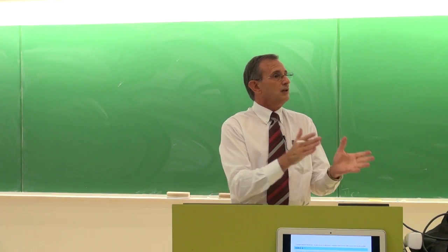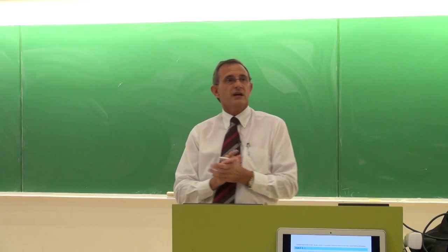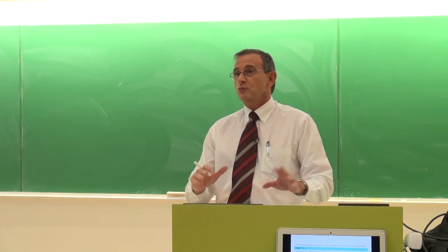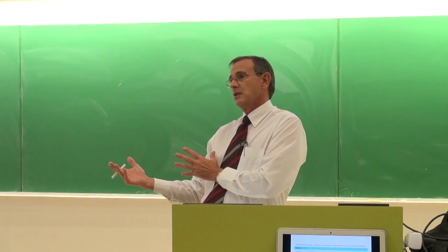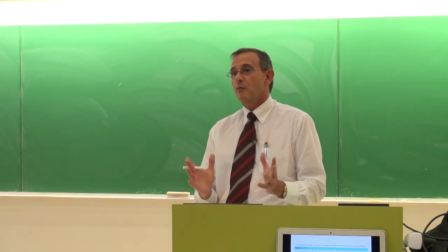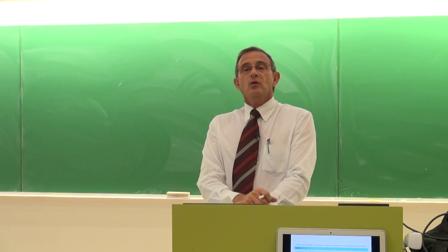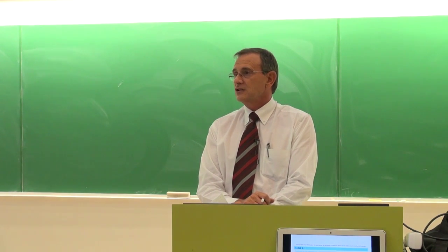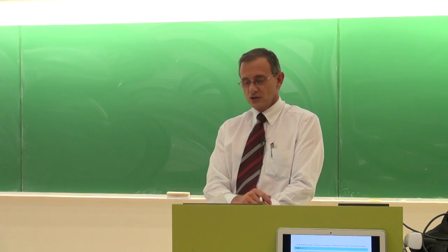That is the complete result, but then there are some easier cases or cases where assumptions were made. For example, if you're interested in the temperature in the center, or for the cases when tau is larger than 0.2, where you only have to use the first term. Okay, so that we've done, and we've done an example. We've done the example of the beef carcass, which was at a temperature of 37, which was then decreased in an environment of -10. And we've used an analytical solution. Now, you will also see in your textbook there's also a graphical solution, and that is called the Heisler charts. And I'm going to show you today how you can use the Heisler charts.